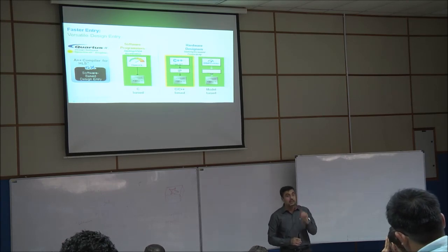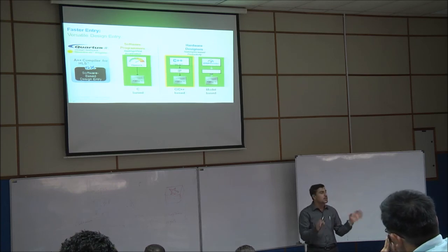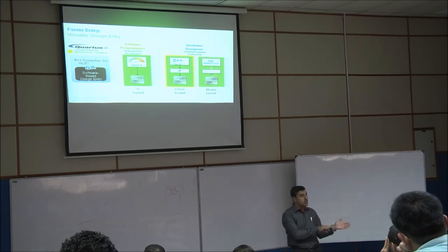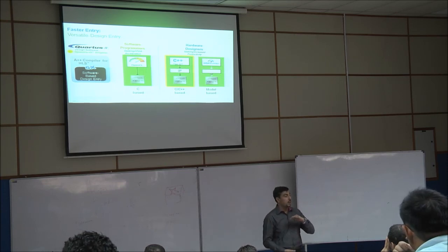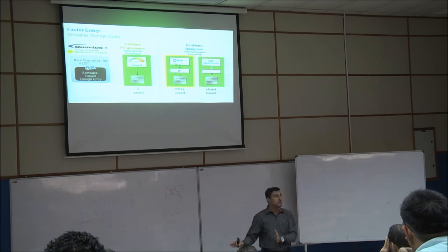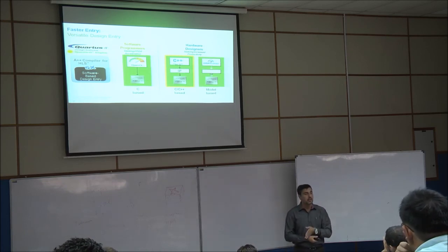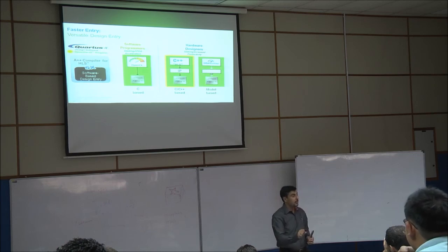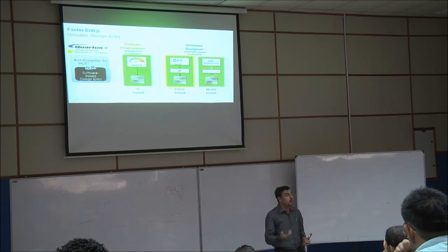So you can build your design by using these modules, just as in Simulink. You know Simulink in MATLAB? Just connect them as blocks, then after everything works well, use DSP Builder to generate the HDL code, whether VHDL or Verilog, because at the end we have to send HDL. Clear? When you generate by using DSP Builder, you cannot touch the VHDL or Verilog, the HDL generated from blocks. Why? Because it was already converted from blocks to HDL by machine, by the compiler.